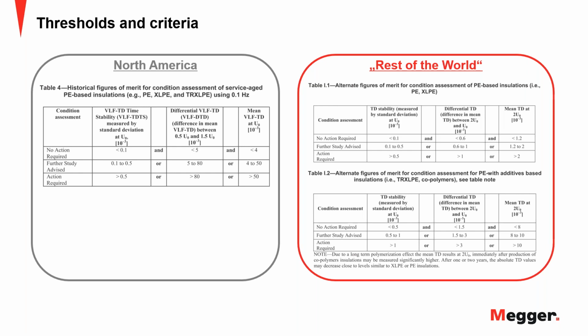If I only look for the decision of which cables to replace first, I'm really looking at the age deterioration of the cable, not necessarily at a specific localized defect, which could be a bad splice. A bad splice I can fix and the cable is fine again. But if I have a cable that has been thoroughly aged and is on the brink of failing, I have no recourse to do anything. So from a cable replacement standpoint, that cable I need to replace, and the only information I need for that is the aging information.